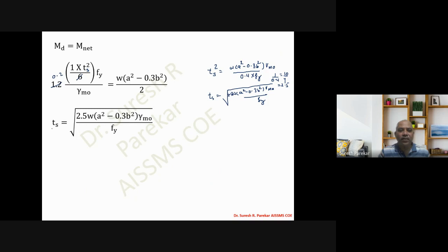We have this formula for the thickness of slab base given in the IS code, but this is how it comes. And this value should be greater than the thickness of the flange. And then we have the last item, the connection between column and base plate. Generally, welding is preferred. If you go for bolting, then you require connecting angles for the slab base and column.